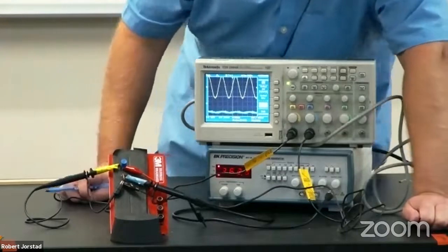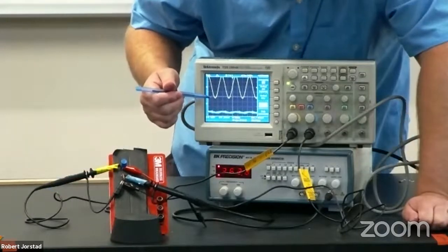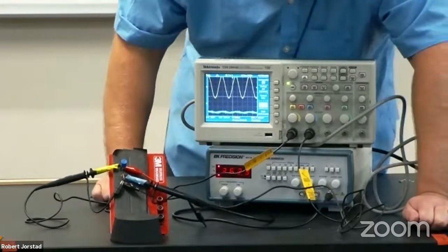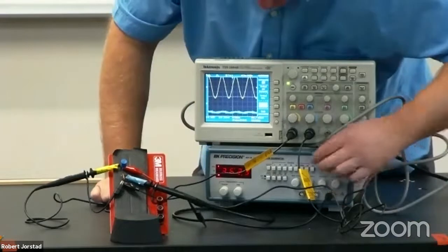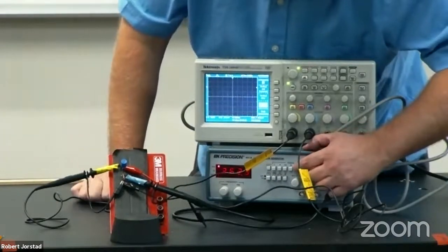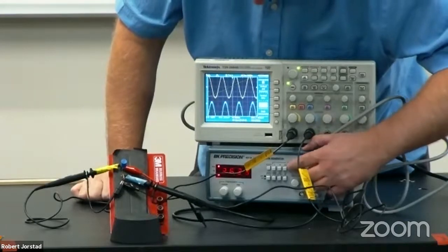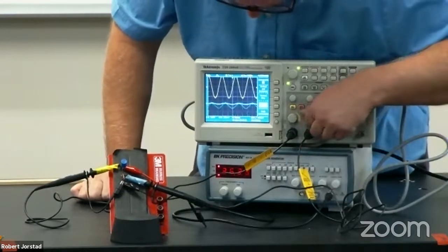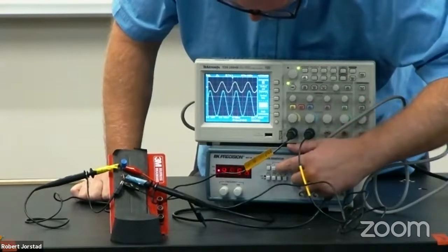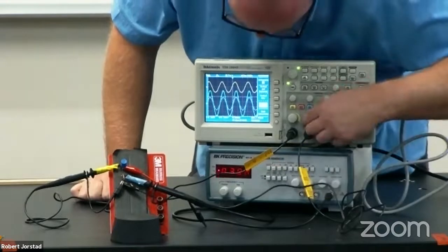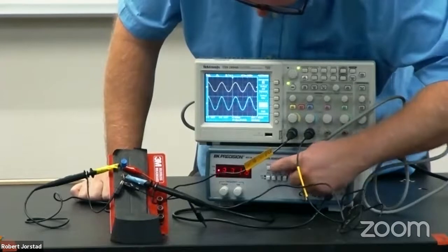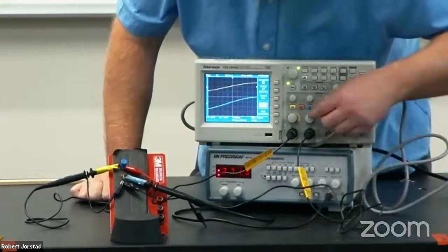So another thing that's interesting is at high frequencies, the inductor doesn't allow current to pass. What if we go to really low frequencies? Well, if I start lowering this down, I'm going to auto range just so you can see it. Here we go. As I start going down, you can start to see that current growing. Let me get these two at the same scale now. That looks about right. As I get lower and lower, notice the inductor doesn't matter at all.